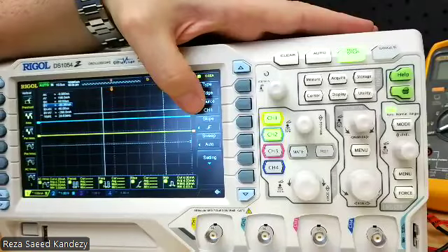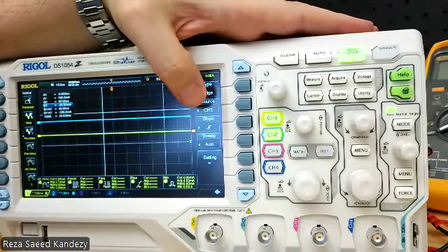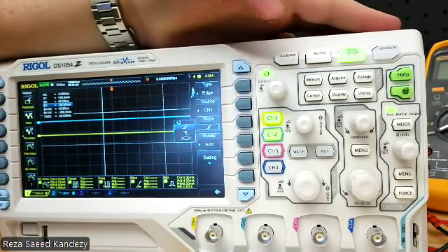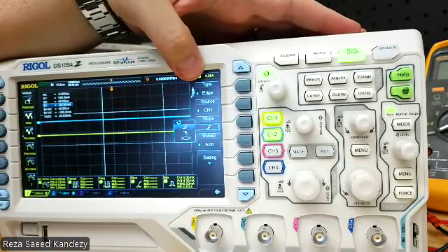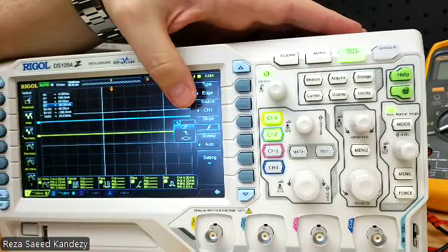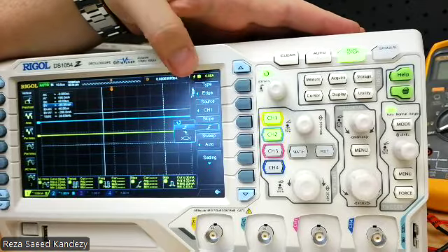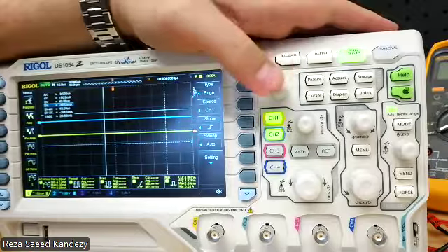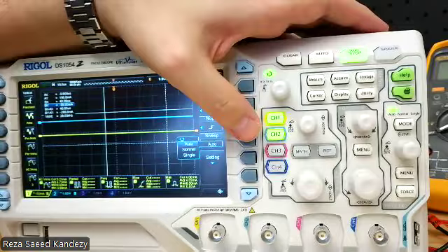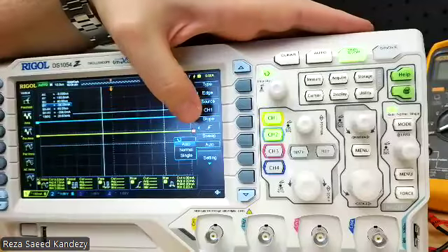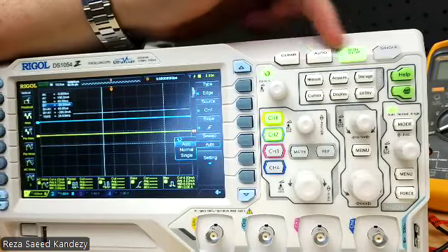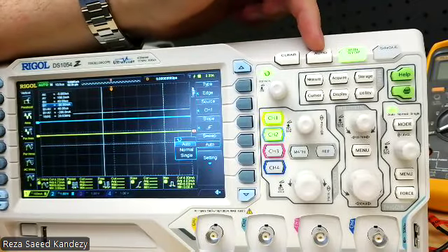Next one is the slope. For the slope, it shows you, for example in the edge, that you want to trigger based on the rising edge, falling edge, or a mix. Again, we don't change that. There is a sweep, which we normally put in auto. But there are also some buttons here that relate to the same modes of